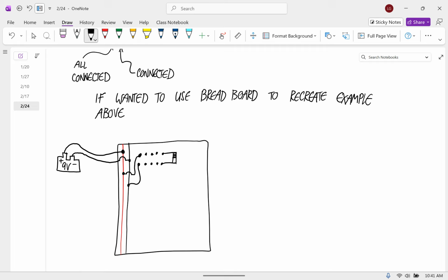The first 2 are a 2-digit number, and the third one is the power of 10 that you're multiplying it to. So if you wanted like 100, say, actually one of the ones I gave you is 100. So 100 would be brown, black. You'd want it to be 10 times 10 to the 1. So it would be brown, black, brown.